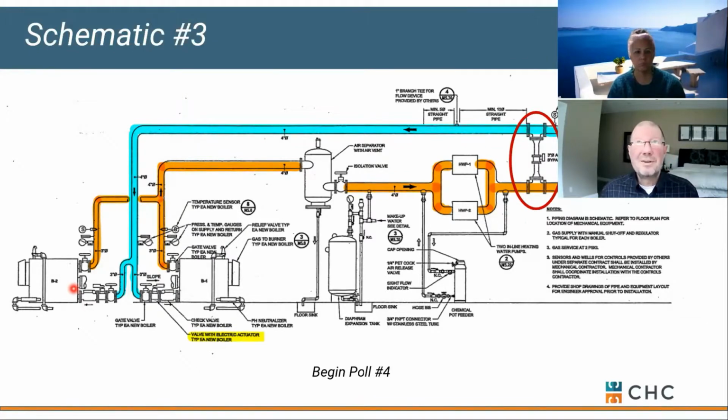But you have to be careful. If your drawing's not to scale, people can space those out and get themselves into trouble, right? If your piping gets too long. But yeah, it's a valid point. To me, it's always good practice to go reverse return. Sometimes you don't have the room for it, so you take your chances. But if your equipment's close together, I'm going to agree with you that it's not the end of the world.